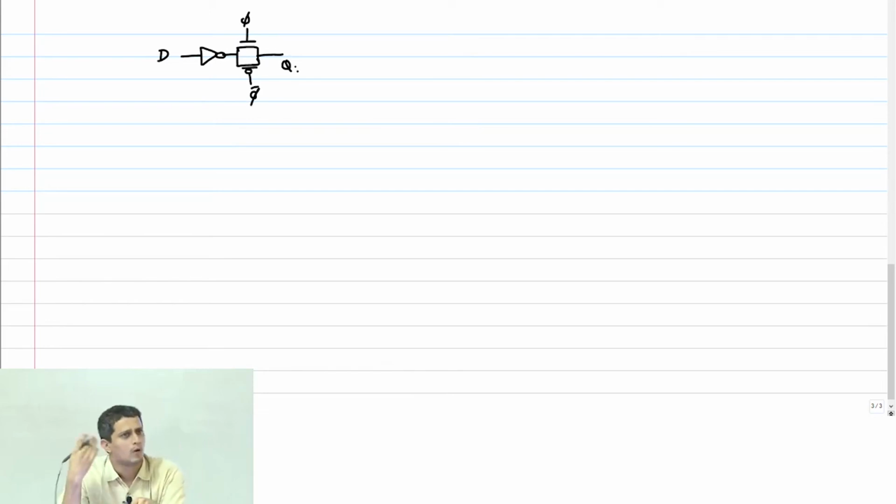So now I can change this concept of an inverter followed by a pass transistor, right? This was D, phi, let's say phi bar. You got something here. What was the alternate circuit I said that can be used instead of this? Cascading an inverter by a transmission gate.